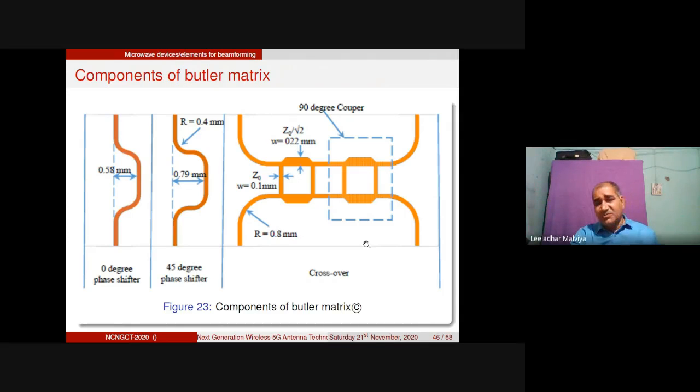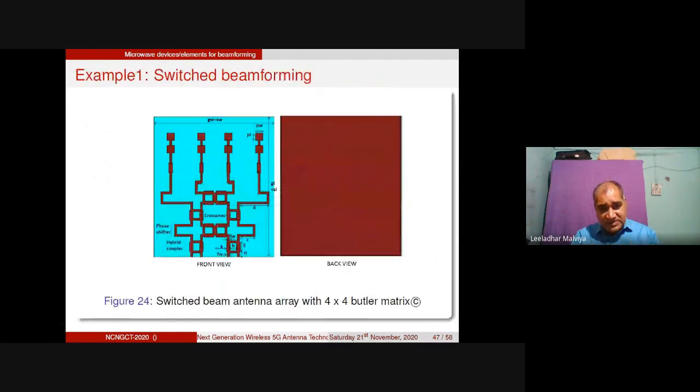So now let us combine these other things. These elements of beamforming can be combined here. If you look at this design, it is based on the Butler matrix. We have designed this 4x4 Butler matrix, having the hybrid coupler, phase shifter, and crossover designed here, right? We designed this Butler matrix for a 10 gigahertz application, and with slight modification, you can show coverage of plus minus 45-degree directions as well as plus minus 10-degree directions at these 4 ports, right?